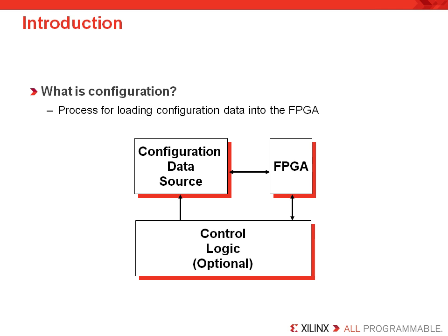This brings to mind the question, why are FPGAs made with SRAM logic and not flash if reprogramming is going to take extra effort and cost? Well, the answer to that is that SRAM cells are much smaller than flash cells, and FPGAs offer much larger densities than CPLDs. So, since we are using a large FPGA, we need to plan on having a memory component somewhere that can store the FPGA's bitstream.